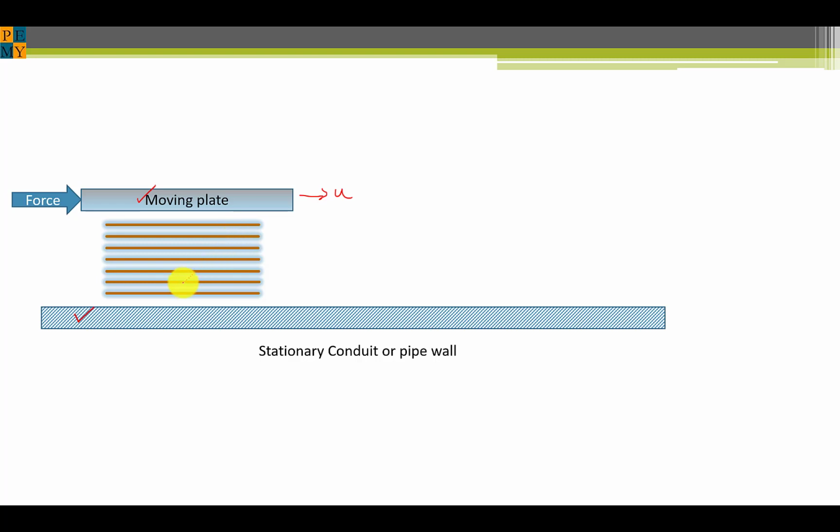There's another point that's important to understand, which is that this layer, which is closest to the stationary plate, is stuck to that plate. It doesn't move. I call it the sticky principle. It's also called the no-slip principle. The same is true with this layer. So this is stuck and moving with velocity u. So let's look at the animation and see what happens.